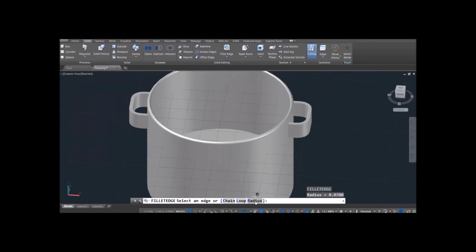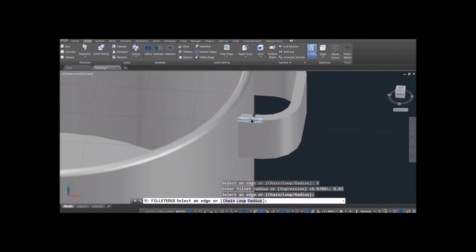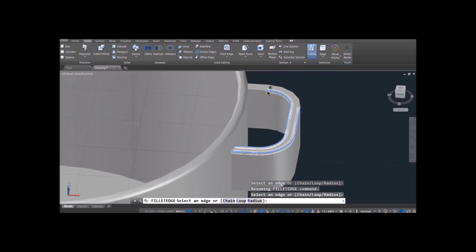If we walk around the handles, we're going to need a smaller radius for the handles, otherwise it won't do it. So I'll make a teeny radius for the handles, and this has all kinds of little chunks on it, so make sure you grab each of those. Just walking around the edge here. If you have a lot of things to fillet, just try one little piece at a time, because chances are one of these little pieces is going to fight you. So if you just do it in small chunks, you'll have better luck with it.